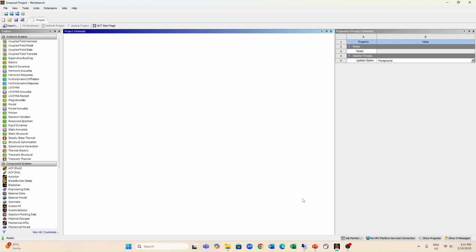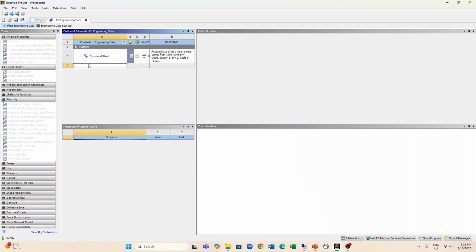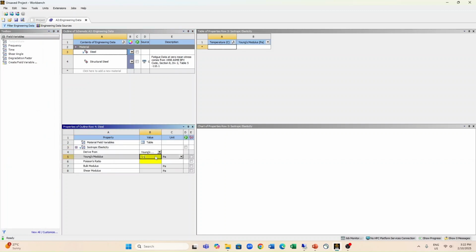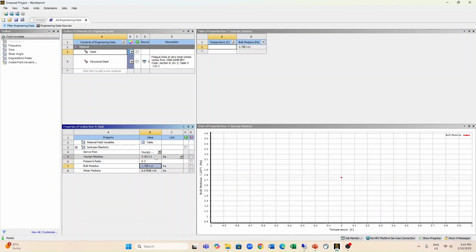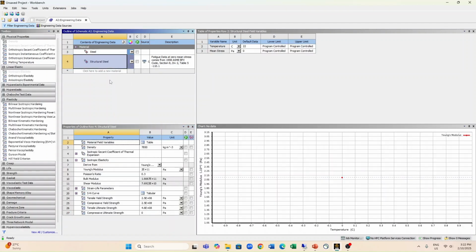Now we go to Ansys Workbench. In Ansys Workbench, for nonlinear buckling analysis, we just need to create a static structural analysis. And for the material, we need to create a steel with Young's modulus 210 gigapascals and Poisson's ratio 0.3. And we can delete the structural steel.